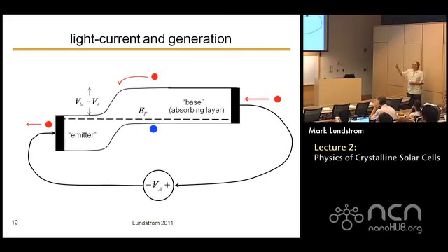Draw this little diagram if that electron-hole pair is generated in the depletion region, and you'll see that only one electron flows in the external circuit. It doesn't matter where the electron-hole pair is generated. Right? So, of course, he discovered that shortly after his paper was published, and in the following paper he pointed out, oops, I made a mistake. That happens. All right.